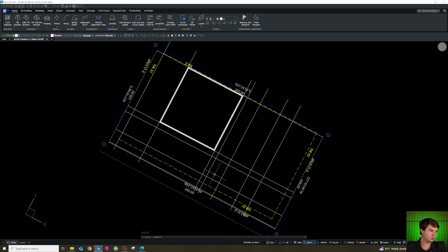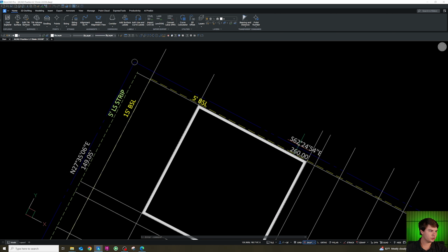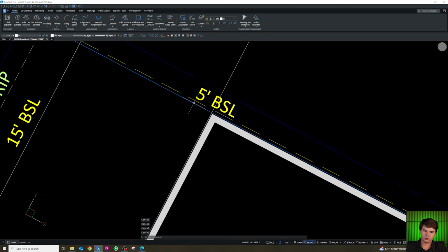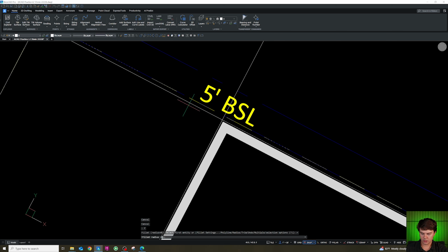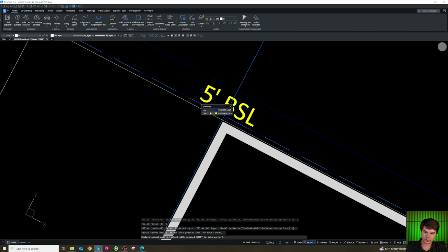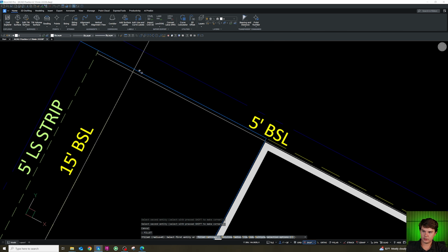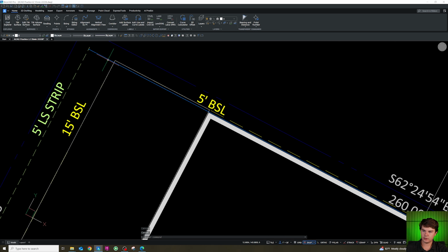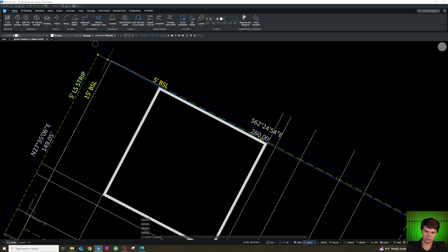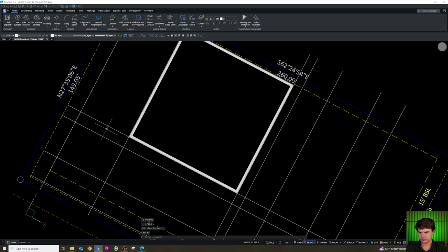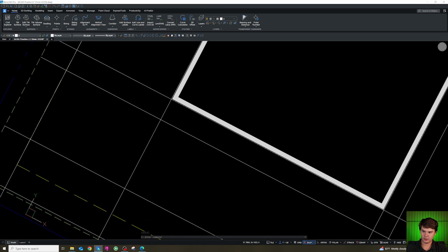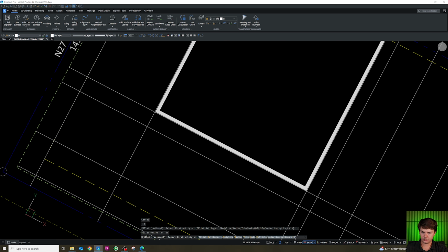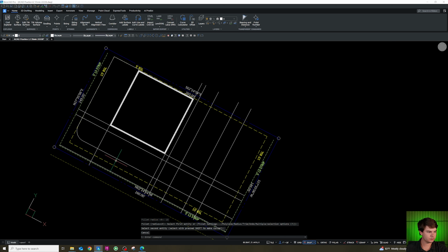Now I would like to start with our drive aisle. It looks like it goes 5 feet from the property line. So I'm going to offset this 5 feet. Then I can use fillet with a radius of 0 to connect, and connect. As so. Now we've got our 37 feet section off for our drive aisle. I can now delete this line for our building. And this will come down, and we'll have a 15-foot curve towards the parking, like this.